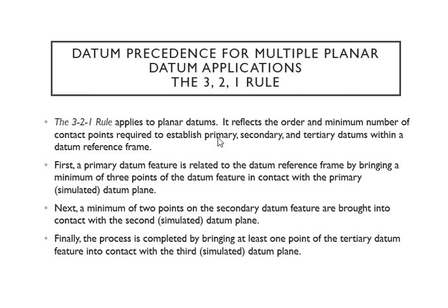So this is how you locate the datum. You can put the primary wherever in the part. You have to have at least 3 contacts in the part. What are the contacts? They are between the surfaces. So if you have only 2 contacts and you call that the primary, then you are wrong. I'm not very strict in grading in this class because you are in the introduction class. But of course, as you go up, and also when you work, these are the checkpoints. And if you keep giving wrong answers, of course, you get fired.